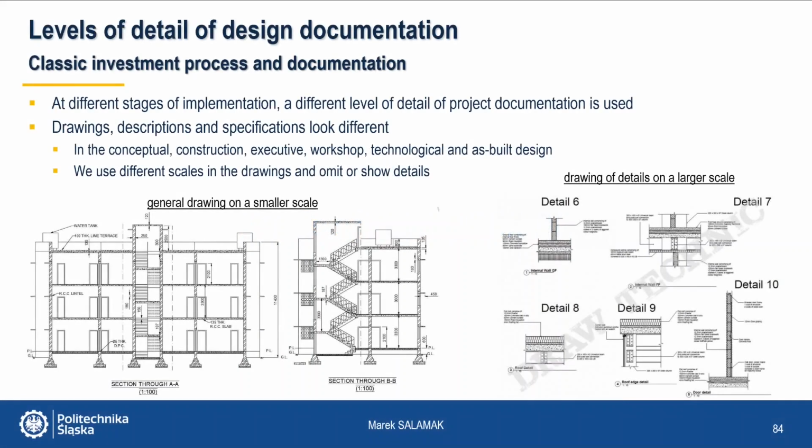The last issue to be discussed today are the levels of detail of the BIM model. In a classic investment process, at the various stages of its implementation, a different level of detail of project documentation is used, design documentation. Such documentation, drawings, descriptions, specifications, looks different at the concept stage, different in the construction and workshop design, and still different in as-built drawings.